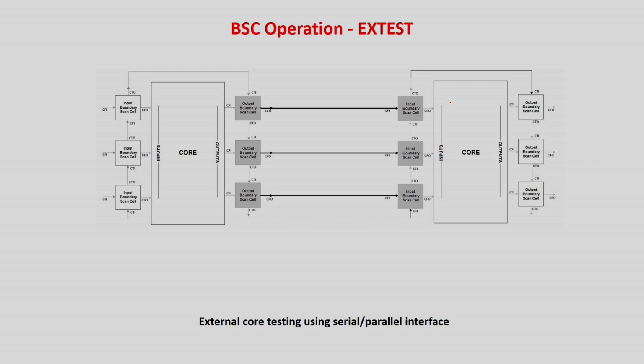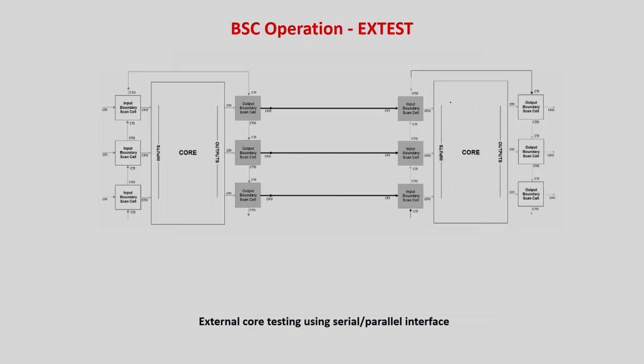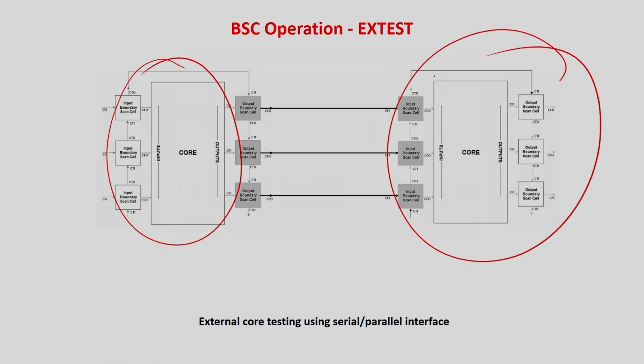Another very important one is X test. Sorry, bypass is a functional mode, not at all a test. Importantly, X test, because this is what I have purchased. Now I have made these interconnections. How do I test it? Testing is very simple. You apply a 1, get a 1. Apply a 0, get a 0. That way, some pattern sensitive values can also be given like 1, 0, 1, alternate, because that means there can be interference between the lines.